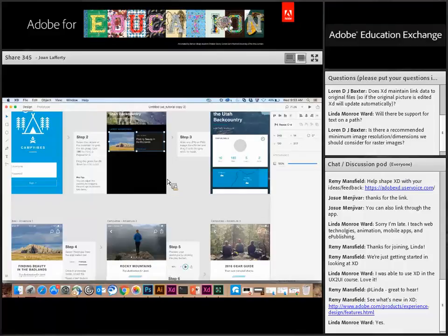Hope that makes sense. And then the last thing was exporting, and you could have multiple ways. So I went up to File, Export. If you have nothing selected, you can actually export all of your artboards, which I think is a pretty common use case that people have. If nothing is selected, you export all your artboards. If you have any particular item selected, for example, maybe you want to export that particular icon,